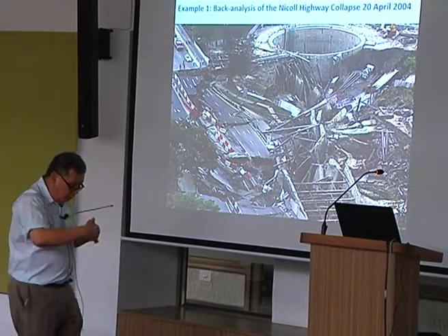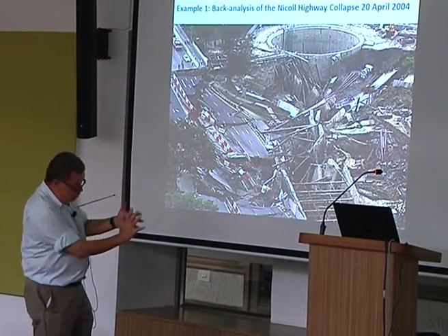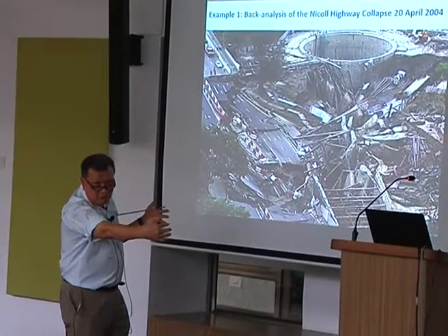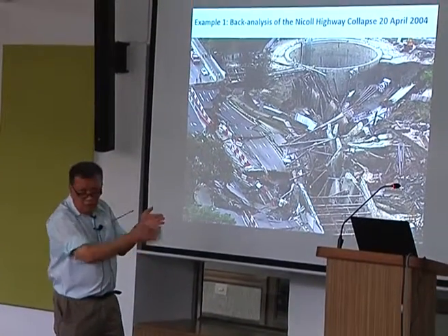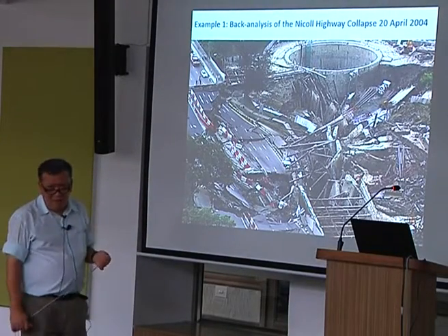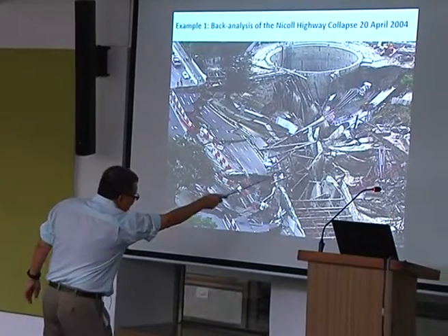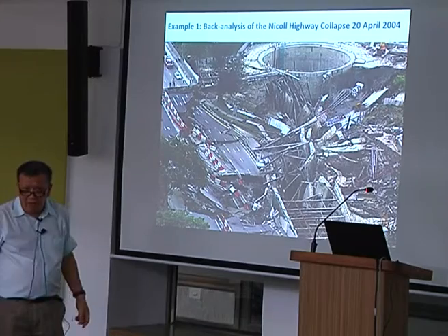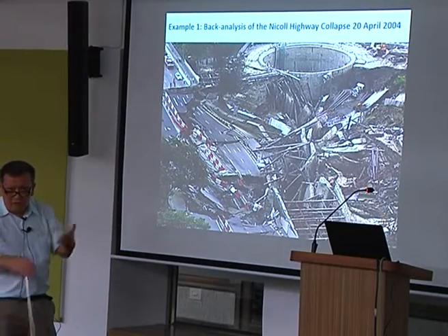So the wall is moving in, but something is pushing the wall in, but it's on a curve. So the guy has got to become longer. How does it become longer? The joints are cracked up. You see? You can see. Every one, like a tombstone, every one. It's all cracked up like that.